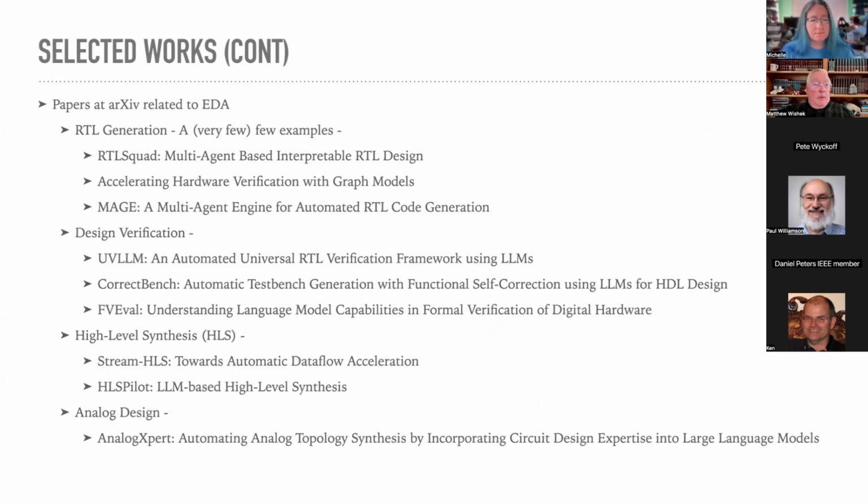And then we talked a little bit about high level synthesis earlier. High level synthesis is powerful in that I can just write C code, simulate the C code, and verify the C code meets the performance specifications. But traditionally you take that C code and then you have RTL designers implement it, and then you run vector matching between the C code and the RTL code, and that way you verify the RTL. But if you could generate RTL automatically from the C code, that certainly gives you a leg up.